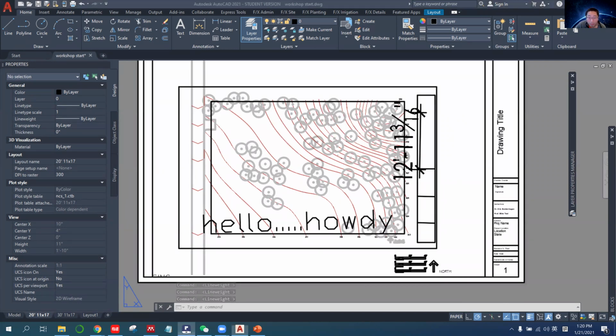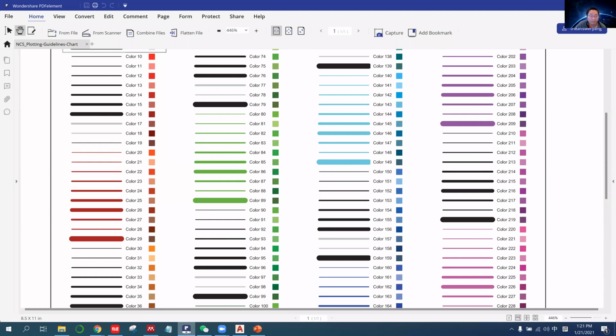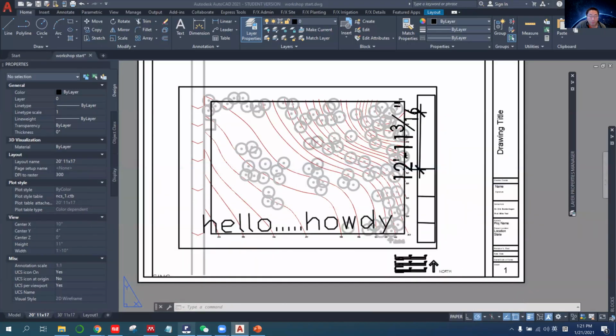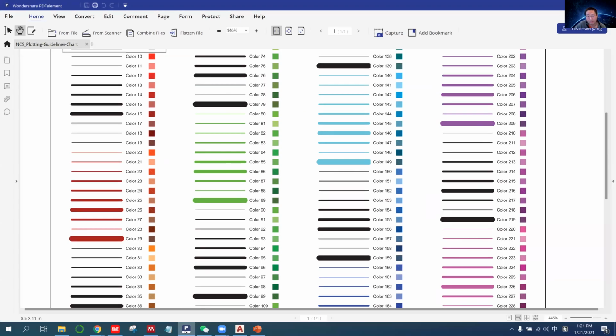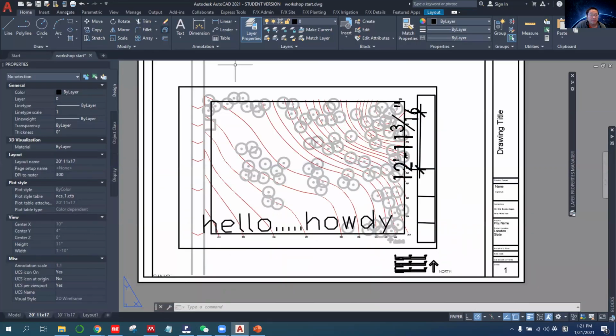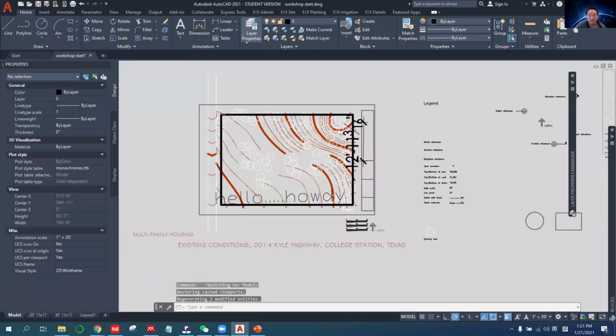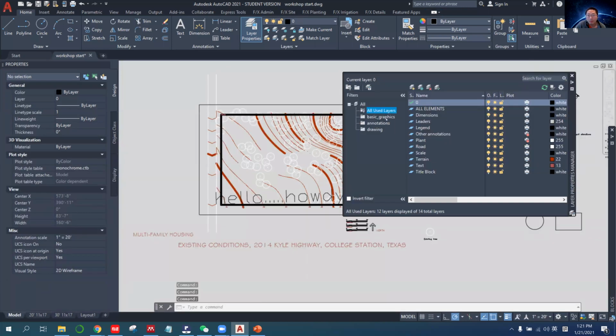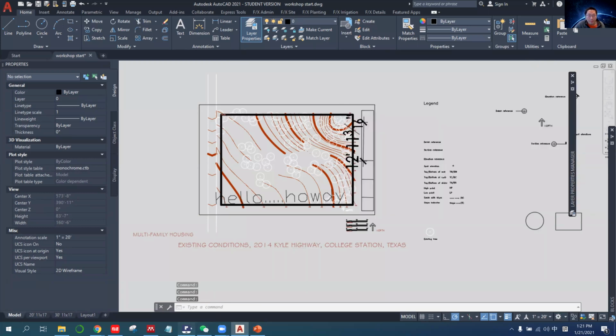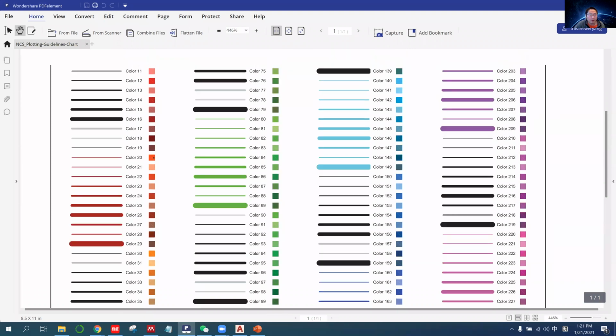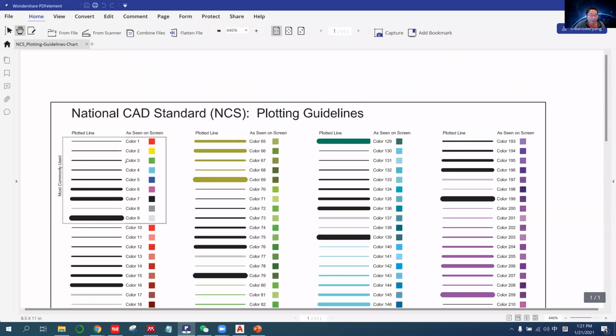So use the pen table and it will save you a lot of time later. The reason is you can set up the layers. If I go to model space, for example, all the basic graphics, I want them to be all black, color 3, and let's say this thick, level 3 in terms of line weight.